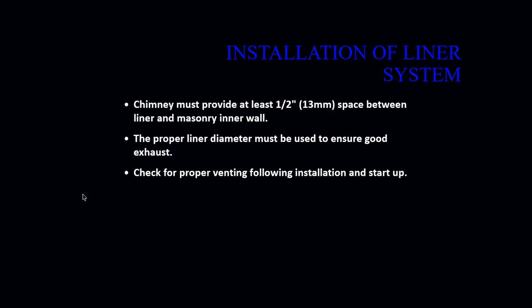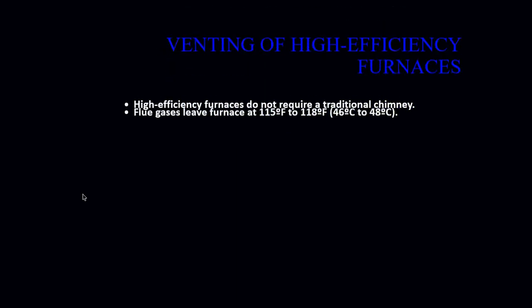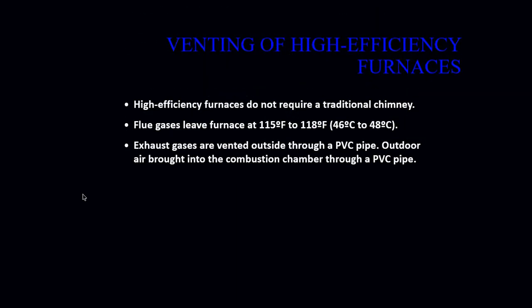Always check for proper venting following installation and startup. So you would actually do a combustion efficiency test to make sure that you do have the proper draft going up the chimney, and make sure that we are exiting and releasing the proper amount in order for this to work properly. High efficiency furnaces do not require a traditional chimney.